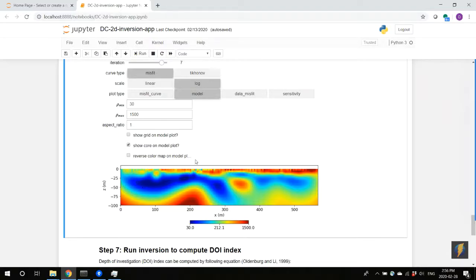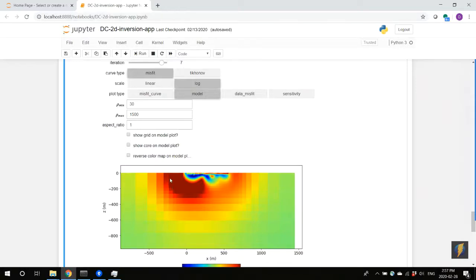So another thing that we learned before we start again is that our initial estimate of the background resistivity actually seems pretty reasonable, maybe it is a little bit lower. So maybe the initial resistivity is more like 250 or something like that. We could also zoom out and not just look at the core region. So yeah, the background seems to maybe be a little bit more resistive. And so now that we know this, we're going to do another inversion.